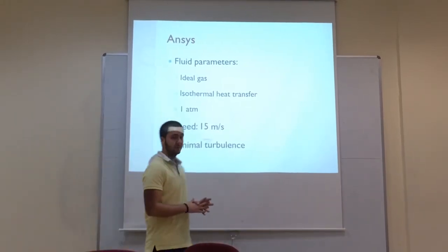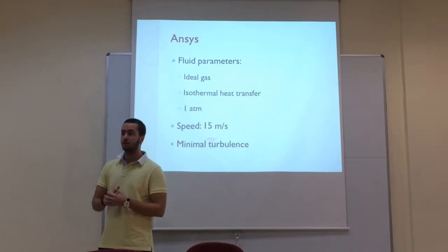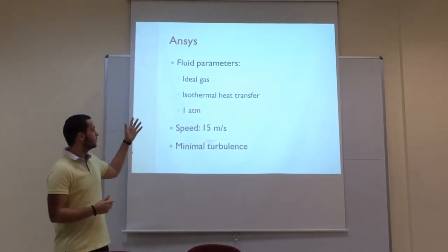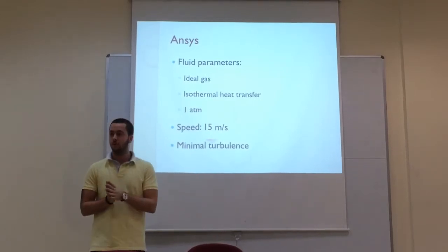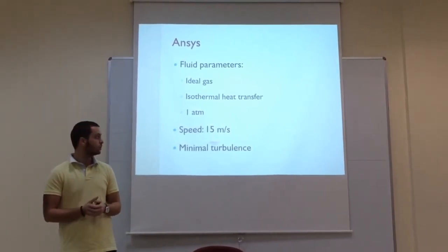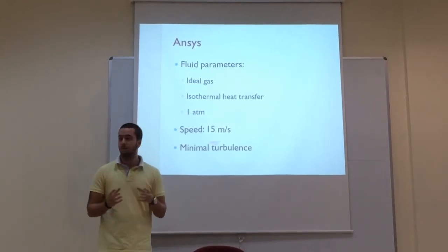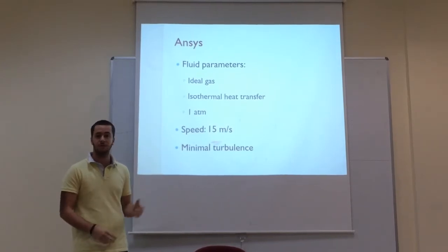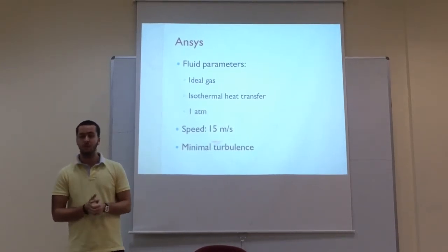Good morning, everyone. As my colleague said, I am Bashar Dadouch, and I will be talking to you about the rest of this procedure. So when we went into ANSYS, we were supposed to pick our parameters for the car and the airflow around it. We chose to pick something that is basic. So we chose ideal gas, isothermal heat transfer, and a pressure of 1 atm.